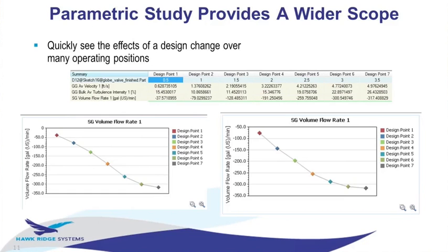As we find out, it looks like making that shallower angle does make the valve operate a little more predictably at the near closed points, but it also tends to make the flow rate drop off as it opens up the rest of the way. So maybe we need some more tweaking to make sure that when you open the valve, it doesn't all come out at the beginning.